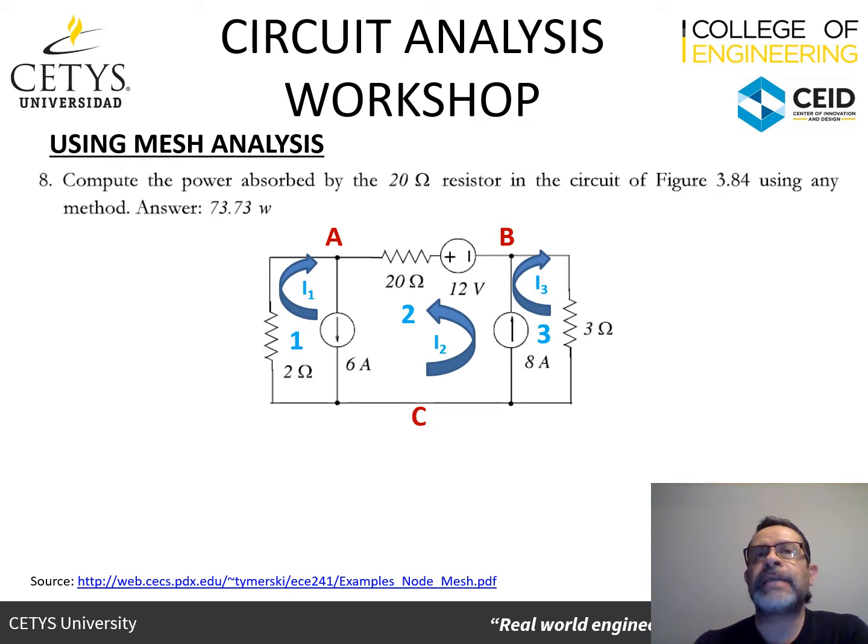Now, setting up these currents in either clockwise or counterclockwise, it doesn't really matter. Remember that in the end, when we do the calculations, we are going to get positive or negative signs. If we get the current with a positive sign, it means that we set the direction correctly. If we get them with a negative sign, that only means that the current actually goes in the other direction.